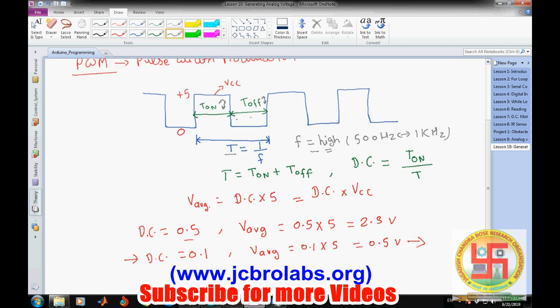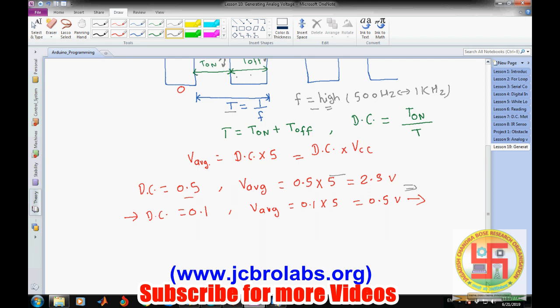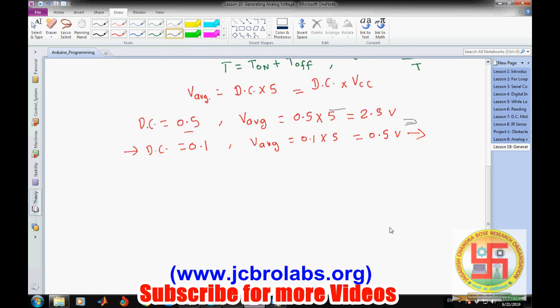Just by generating this kind of pulse wave at any pin, we can change the corresponding voltage available at it. So we will visualize it in Arduino UNO. In UNO there are 6 pins which are used to generate PWM: pin number 3, 5, 6, 9, 10 and 11.